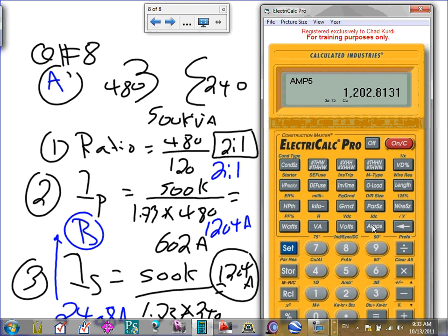When we talk about loads in amps, we don't use kiloamp. Kiloamp is a lingo that we use for short circuit. So at work, if somebody asks you what size switchgear this is, and you say 4K, in the mind of a lot of engineers, that's a 4K interrupting rating, that's short circuit. Usually for amp size of equipment, it's always in amps. 200 amp, 2000 amp, because all equipment guys can go up to 4000 amp, sometimes special 5000 amp and 6000 amp, that's it. But short circuit goes higher than that.